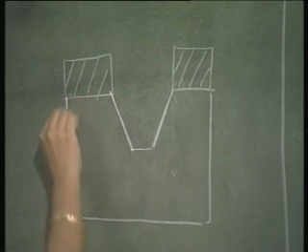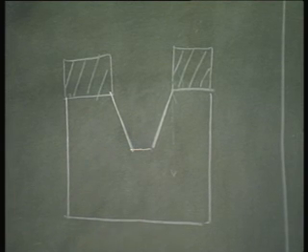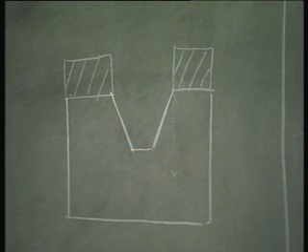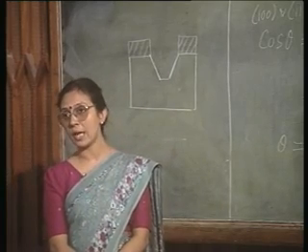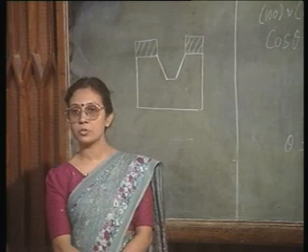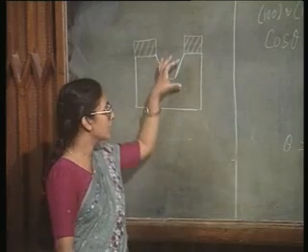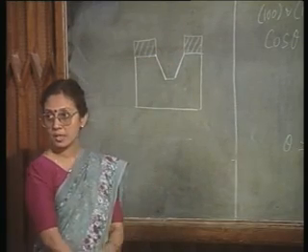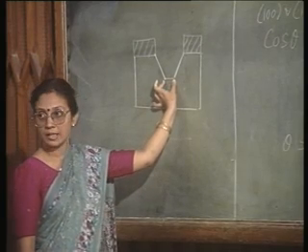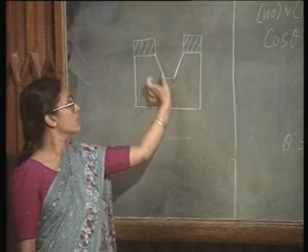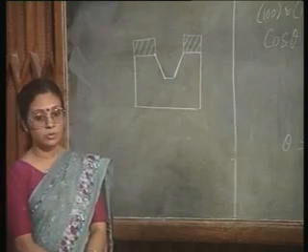So, now this portion can be the source and the drain, and you can have your gate here. So, what have you achieved? You have achieved a MOSFET with a very small channel without actually having to have very crucial photolithography. By deciding the time of etching and by keeping this window dimension, you can actually realize a channel length which is going to be much smaller than your original window opening. So, it is used in VMOS.